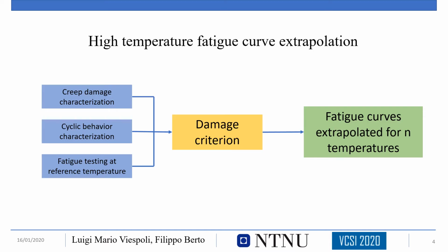The logic of the method consists in an initial characterization of the material in terms of creep damage, cyclic response, and fatigue at the reference temperature. The data are then combined to shift the fatigue curve proportionally to the amount of creep damage induced.